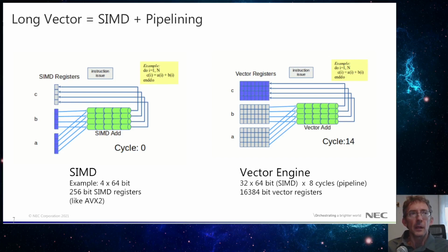You see this is a sketch of a vector operation, vector A plus vector B equals vector C. And when the instruction is issued, the content of the vector registers or SIMD registers A and B are loaded into the SIMD pipeline, in the add pipeline, and processed for a certain number of cycles until the result is delivered to the result SIMD register.